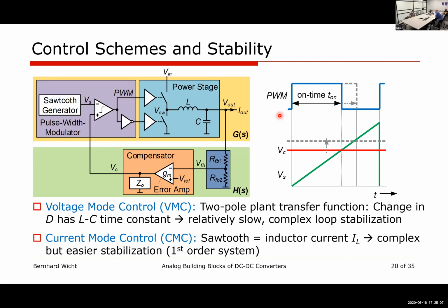Yeah, this is Claudio. Hello, Bernhard. I have actually two short questions. One is regarding imagers: in imagers you require DC-DC converters like charge pumps that have very, very low ripple, in the microvolt range. So can you comment, how well can you control ripple, and what is your recommendation? My other question is if there is some way to benefit from FinFET technology?